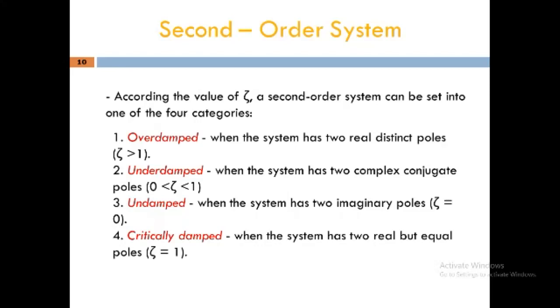Now we are moving towards the contrast of the physical reality. All these transient changes, which are also called the transient response, vanish after their disappearance. A new steady state operation is established, and in this respect, we may say that the transient describes the circuit behavior between 2 steady states, the old one which was prior to the change, and a new one which arises after the change. A few methods of transient analysis are known: a classical method and the Cauchy's Heaviside method, which is called the CH operational method.